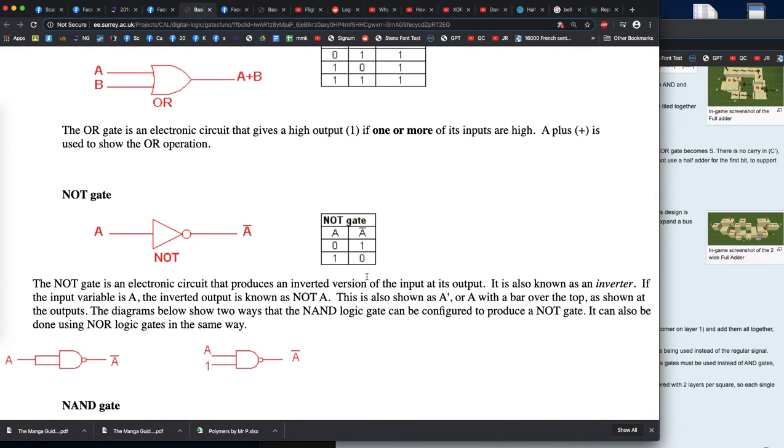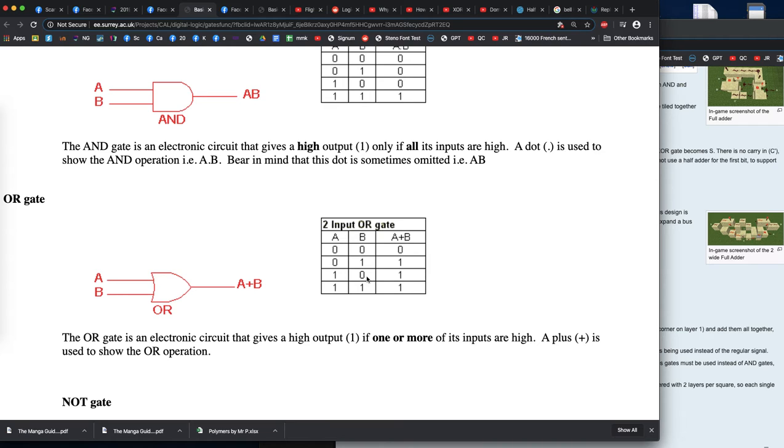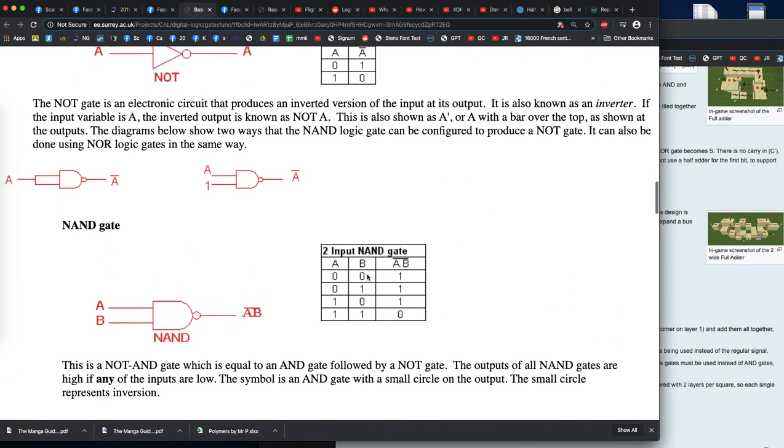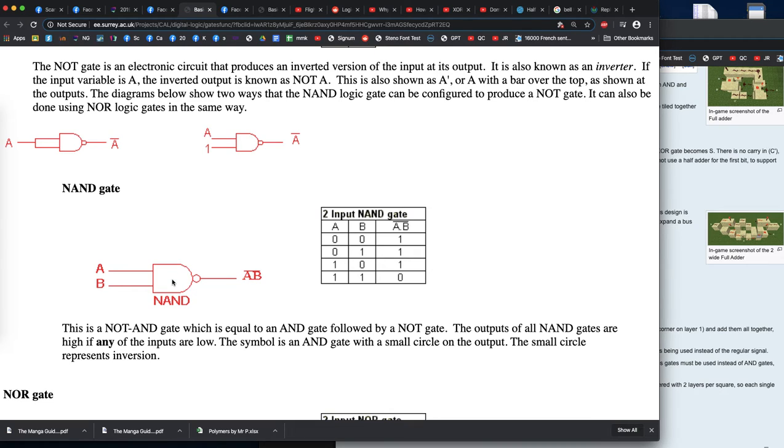The NOT gate is like a crazy manager who, every day it's Bizarro World, and just says, "Hey, you know what that gate was going to say? I don't care. Just do the opposite." Right? So if you have a NAND gate, I always write the answer for the AND gate in the middle, and then on the outside, I just reverse it. So in this case, neither of you on the list, you're both in. Bob's on the list but Alice isn't? It's okay, you can come in. Don't worry about what that bouncer says. If Alice is on the list and Bob isn't, don't worry, you're both in. I'm changing the bouncer's mind. If you're both on the list, the Bizarro manager says, "Sorry, you can't come in," right? The NOT gate. It's just crazy.